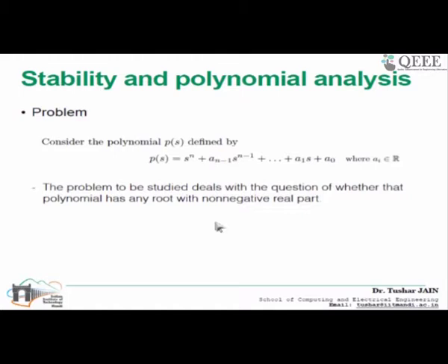Based on this polynomial you do the stability analysis. The tools I listed in the contents in the very first slide will be applied on this polynomial, because as we have seen in the previous lemma, it gives a very strong result: if I can prove that the roots of this equation lie on the left hand side, this means that the system is internally stable.